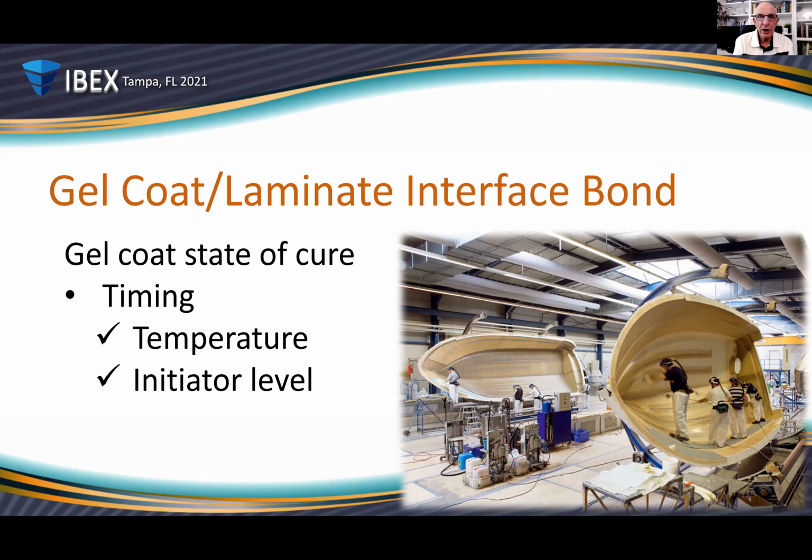Basically, if you're going to gel coat something, you need to have the time in the day to get at least a skin coat, a pre-laid laminate, down on top of that gel coat so that you don't have the problem. Now with laminating resin, you don't have that same issue because it's not made to cure like a laminate. If you get a skin coat on a Friday afternoon and you come in on a Monday, you just scuff it. You just quickly grind over the surface and you're good to go. It's a little bit of a different situation there, but with gel coat, that timing is very critical.